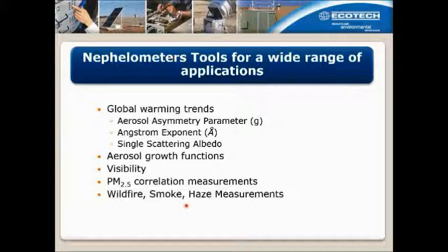Yes, there was a question about normalizing the nephelometer measurements. As I explained, the scattering is dependent on the number of scatterers, and the number of scatterers is dependent on the number of particles in that area. If you have ambient conditions, then the number of scatterers depends on the volume you have, so you have a volume-dependent correction in there.